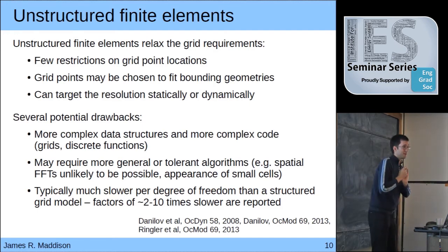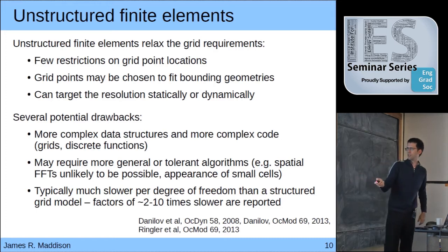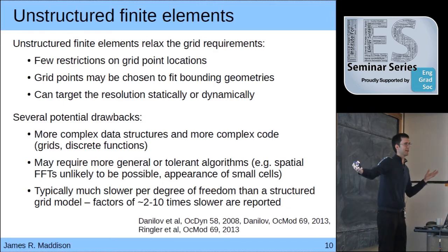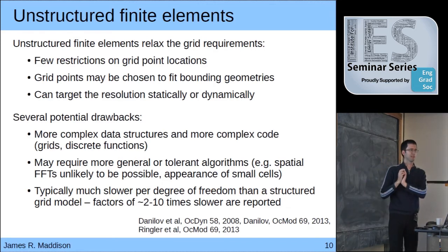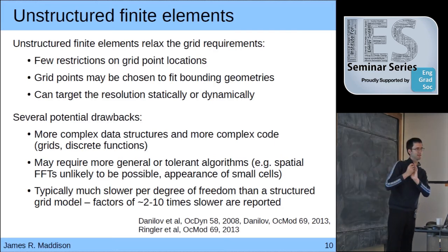The bottom line is the code gets much more complex when you code something like this. The data that you've got on these triangles on an unstructured grid does not map onto a 2x2 array in memory. It's not just a rank 2 array in RAM. It's much more complicated than that. You need data structures to represent the triangular grid itself, data structures to represent the data on that grid, and data structures to tell you how to compute numerical integrals on that grid. It gets much, much more complex.